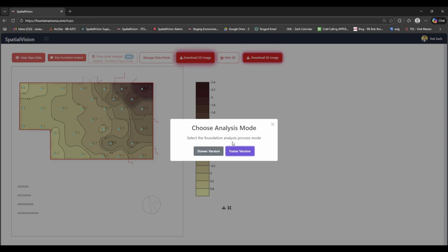The slow version and the fast version, so the difference between the diagnostic calculations for the tilt and deflection measurements: the fast version does 1 pass-through, the slow version does 3 pass-throughs. We can get into the nitty and gritty on the difference between these, but really quickly, with the fast version, our diagnostic calculations are going to take a measurement line from foundation edge to foundation edge. We're going to break that into 9 equally spaced points, and then we measure the up and down variation between those points. And we give you a really simple output on the health of the slab, essentially.